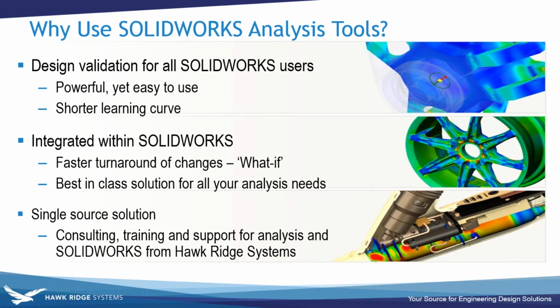Being integrated within the actual CAD makes things a lot easier and allows you to do a lot of what-if conditions. What if my material is this, or my material is something else, or my thermal loads change. But the other part of the integration is that if you have a structural tool and a thermal condition that you want to apply to it, we can run those in separate studies and then combine them together, which is what we're going to see here today.